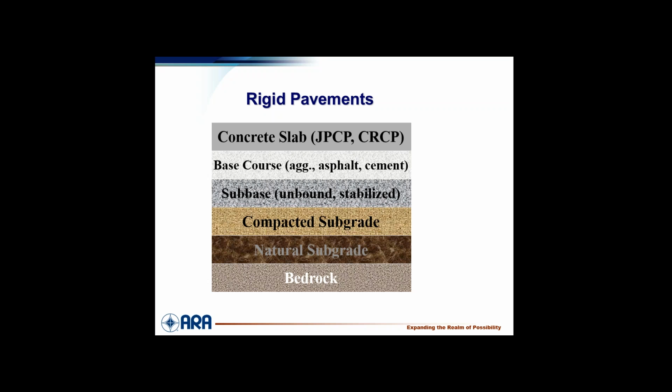Well, that'll be slipping and you'll get cracking within a year or two. Well, on the concrete side, there's also a lot of friction. And there's only one case where really you can lose that friction, and that's where you have a concrete or a cementitious treated base course, and then you can lose that if you try to lose it. But that friction between layers is a really big deal and contributes to the structural design of the pavement in that case. That was one of two big things on the concrete side.